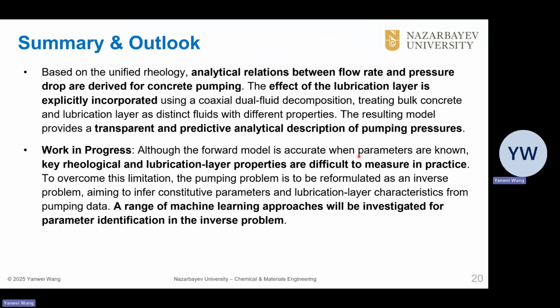However, the practical challenge lies in the measurement. Even if the forward model is accurate, lubrication layer thickness and lubrication layer fluid properties are hard to measure directly, especially on-site. So now we are working towards reformulating concrete pumping as an inverse problem.